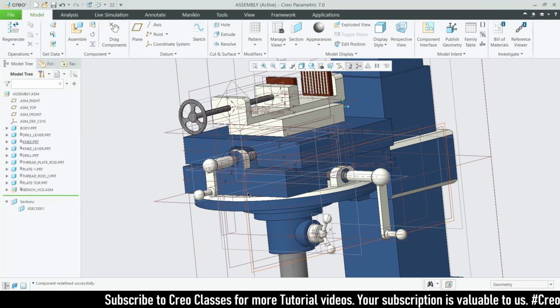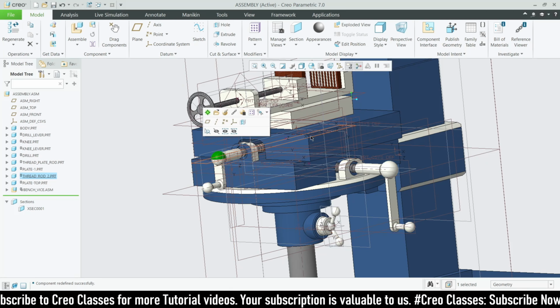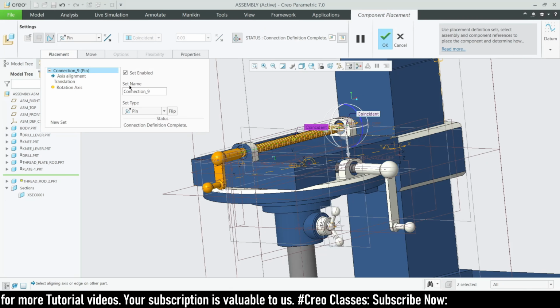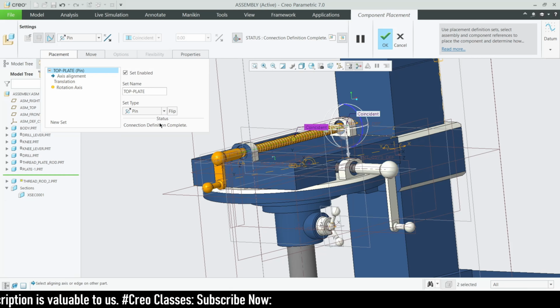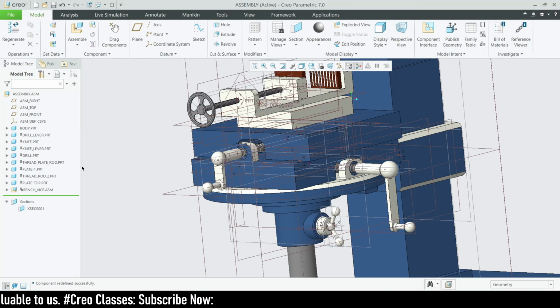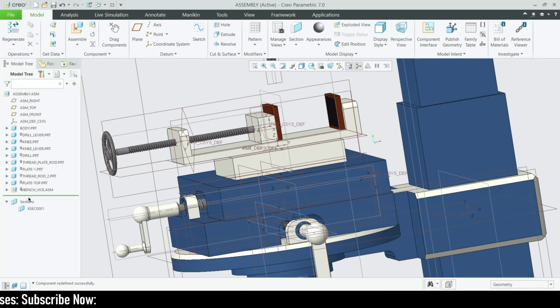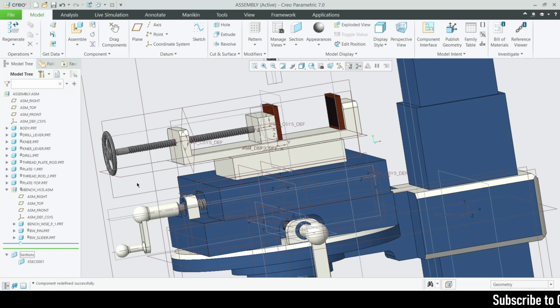And then the next part where we are going to add our motor in here. So this is going to be our top plate movement. Edit, and same we have to edit the name as top plate. And the third motor is going to be for the bench vise. For this bench vise, we have already done the same while creating the sub assembly. I have already renamed it.